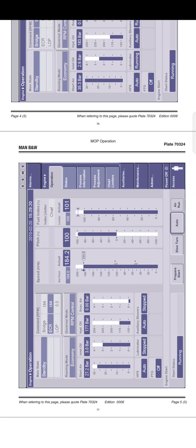Now the bridge control and engine control room stations are part of the RCS remote control system. Only one control station at a time is active. The active control station is normally selected via the RCS request acknowledge system. However, the selection may be overridden from either the ECR or LOP by the take command buttons, which are wired directly to the ECS engine control system and situated on the control station panel.